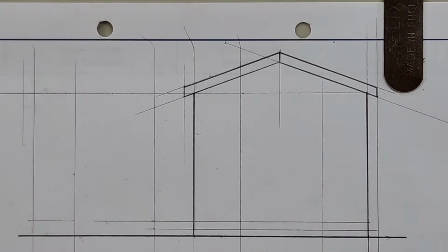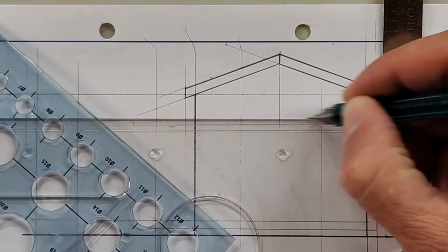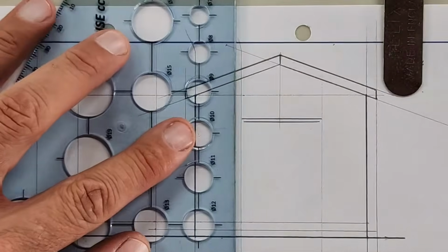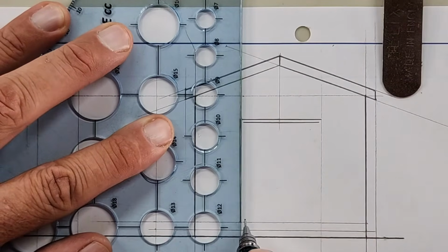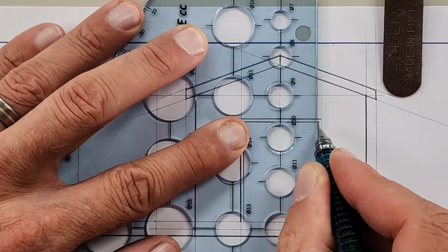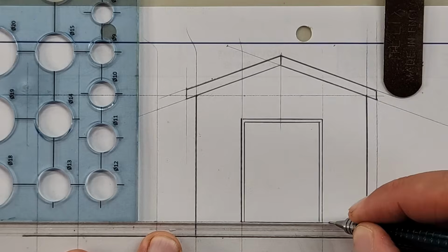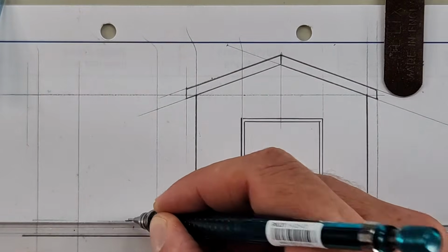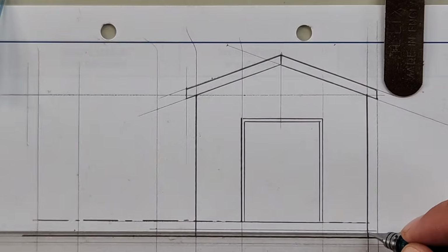Okay, our door, the height of that door is given here as 2,100. Okay, and it is a double line as well. So about 1 millimeter spacing. Up to the finished floor level. Same on the inside. So on the outside. Alright, then we have our finished floor level. So over the opening it's a solid line. Then it goes into our center line type. And it's going to go all the way through to the end here. Okay, then our step, the width of the step, it's the same as here, so that goes all the way through.